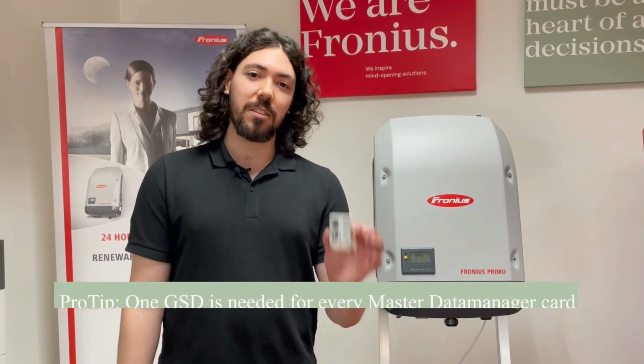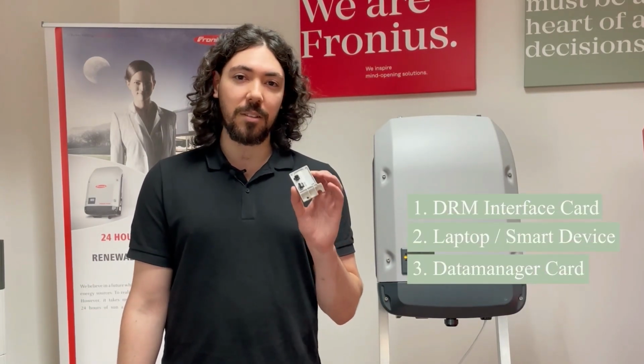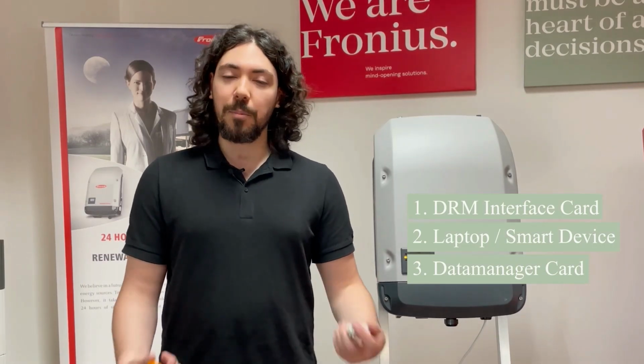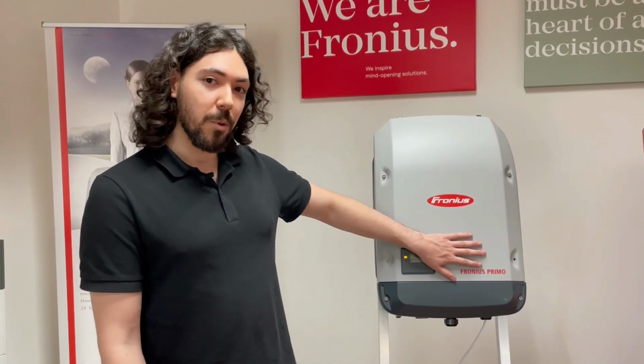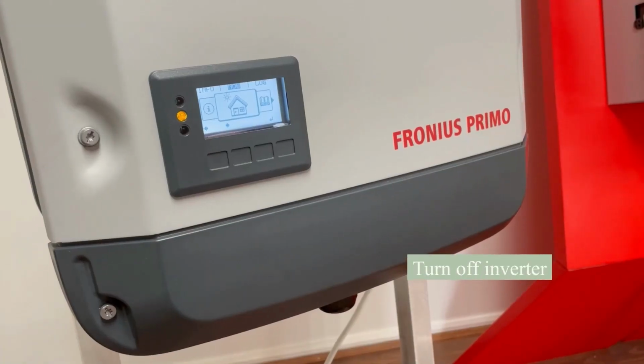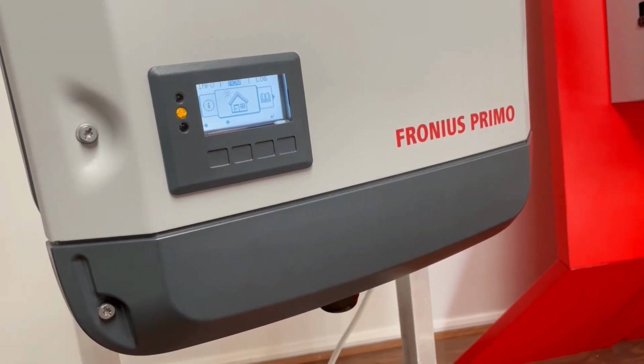So what you're going to need is a DRM interface card. You can purchase one of these from our sales partners as an optional extra. You'll also need a laptop or a smart device, and of course you'll need a data manager card, which is found inside most of our SnapINverters. The first thing is to turn the inverter off before we change any connections inside the inverter.